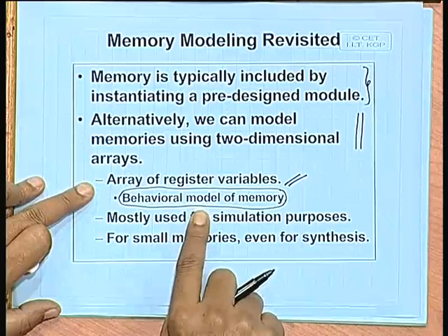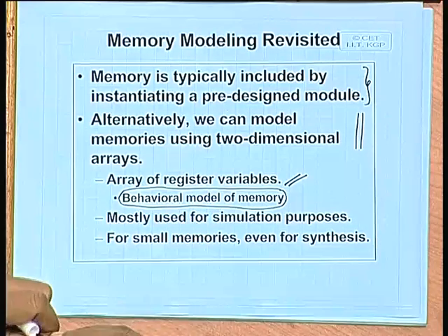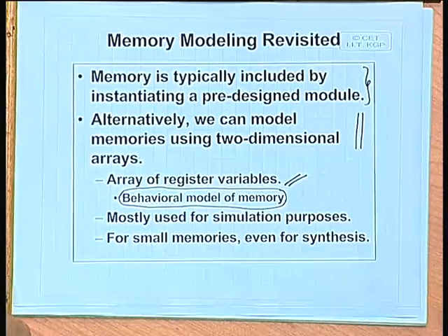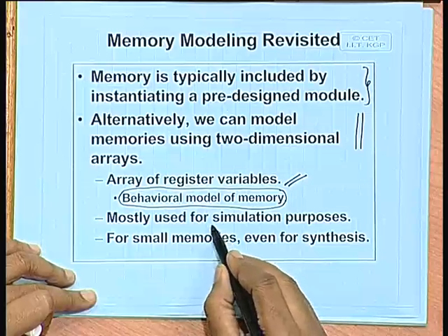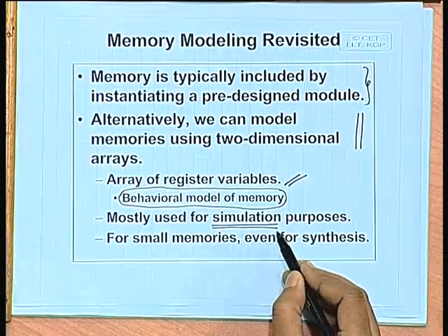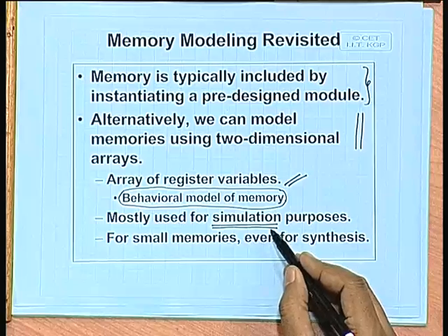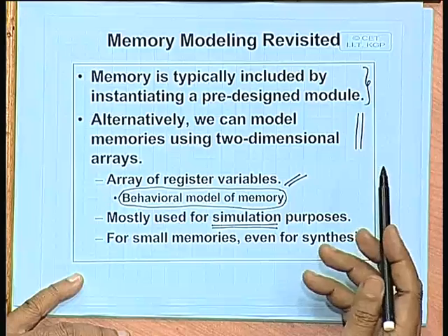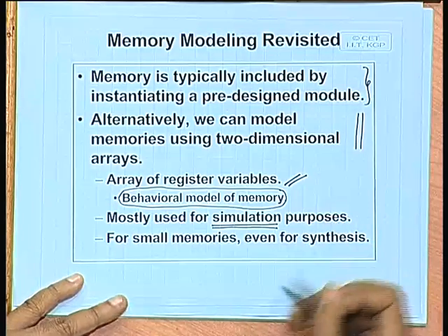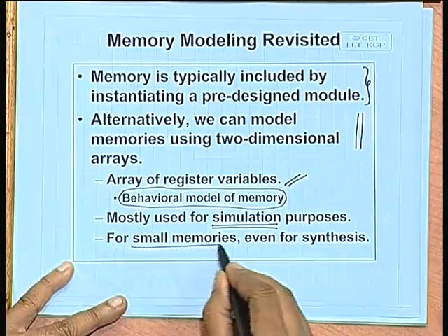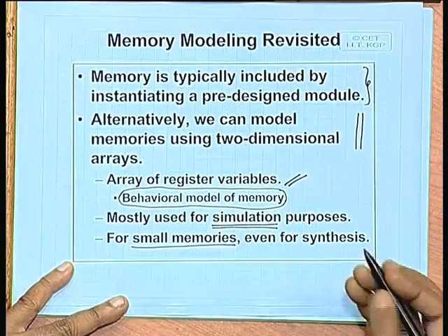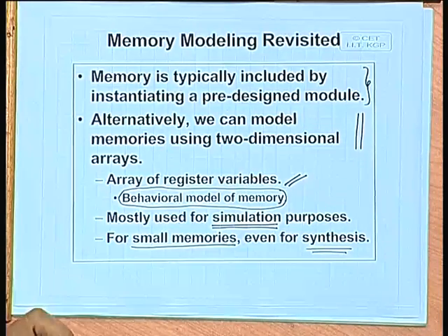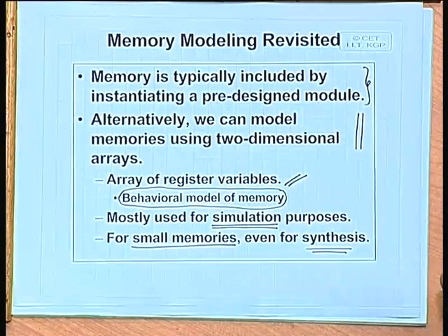Well, actual memory system is not just an array of registers, it is something more than that. There is some special layout and special way they are fabricated, but this view of the memory is often used for simulation purposes. But when you are talking about fabrication, when your ultimate aim is to design and fabricate the chip, then you would have to instantiate a proper memory block from the library. But if you have small memory requirements in a design, then you can use it even for synthesis, this alternate way, modeling memory as a 2-dimensional array. Now, let us see how we can do this.